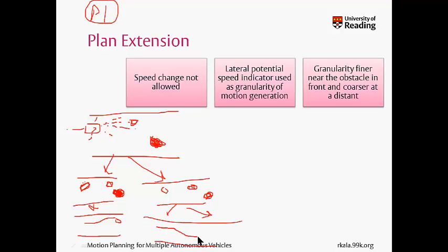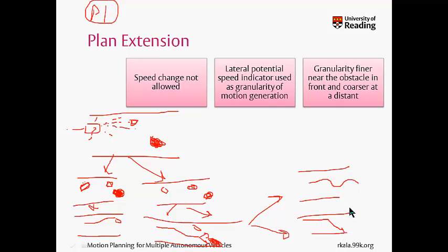My trajectory would be like this until I find a static obstacle, in which case again there are two options. I turn right or left. I compute both these possibilities here. In one case I will have this as the trajectory, and in the other case I will have this as the trajectory, and clearly it can be seen this trajectory is the best. It's longitudinally the most ahead. So out of all these three possibilities, this is what my final trajectory would come out to be.